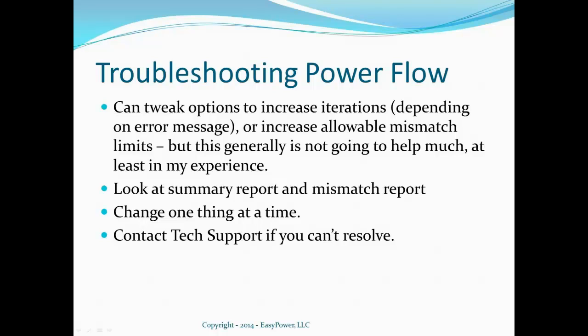When modeling a step voltage regulator, voltage is 1-to-1, but since it is 3 wires in and 3 wires out, do you model it as a YY? Yeah, typically for the step type, I would model it as YY. That's how it's actually going to be connected. So yeah, that's YY.